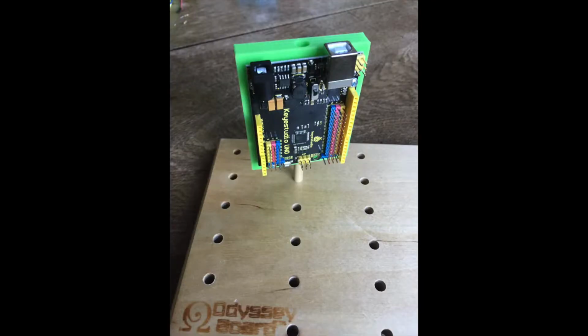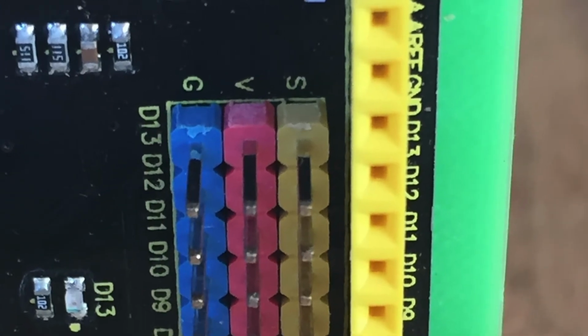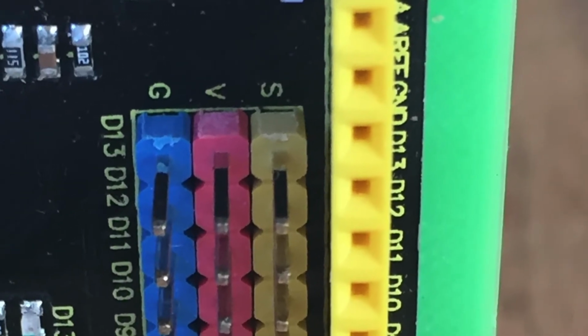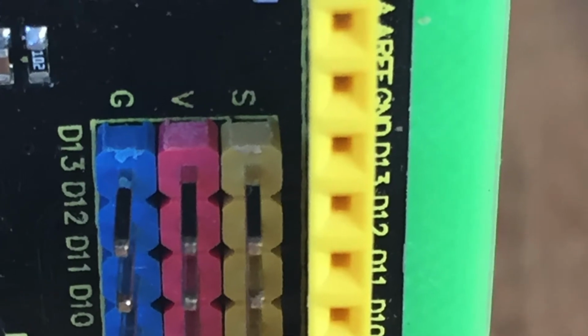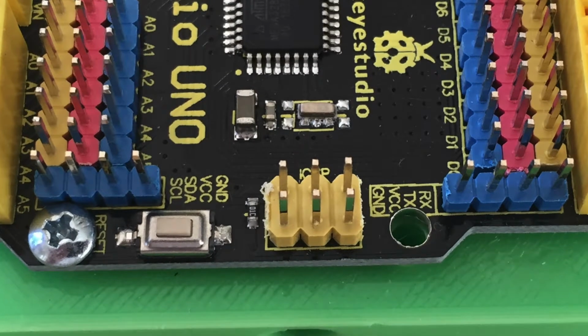Mount the microcontroller to the Odyssey Board base using a dowel rod. Next, we will connect the wires to voltage and ground on the microcontroller. The row of blue pins labeled G are ground, or negative, and the row of red pins labeled V are 5 volts, or positive. Be sure not to connect to the very bottom row of blue pins, as they are